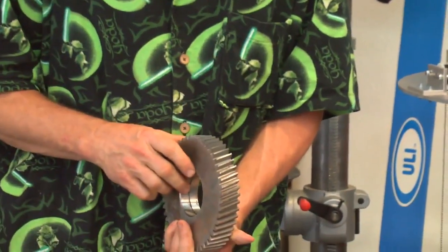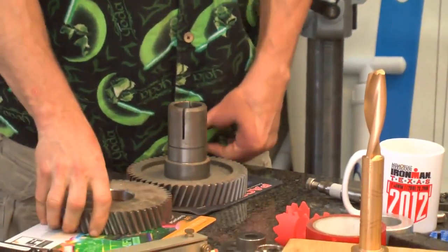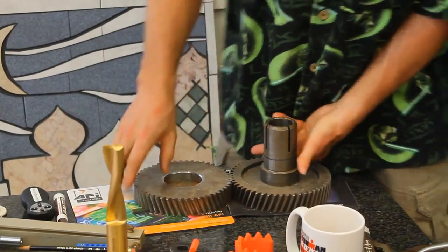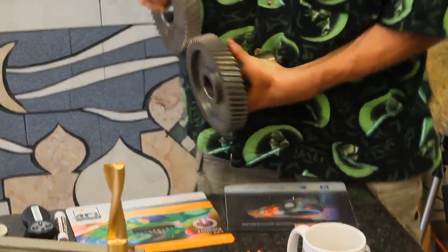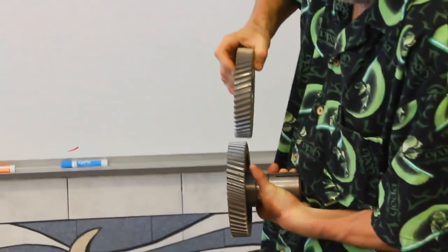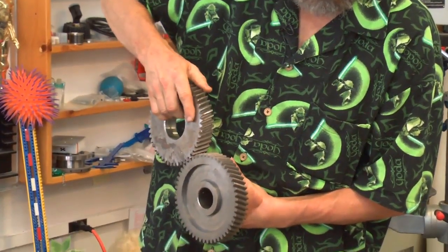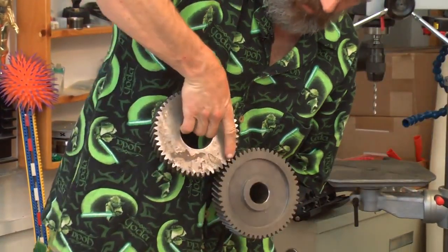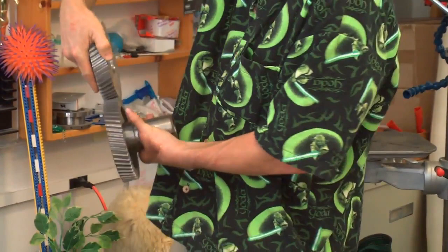And if you ask, whoa, why are the teeth at an angle? Well, what it enables you to do is when they engage, and I'll see if I can pick this up to show it better. They are much smoother because they tend to make contact down, and if you look on the other side, on up.